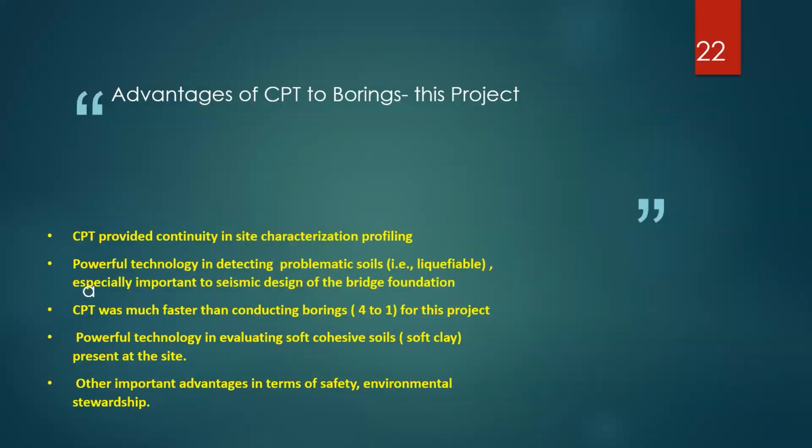So, advantages of CPT over boring on this project: it provided continuity, right? It is a powerful technology in detecting problematic soils, be it liquefiable or other problematic subsoils. It's much faster than conducting borings, almost 4-to-1 as measured on this project. It's also a powerful technology in evaluating soft cohesive soil, soft clay, which was present at this site in some of the bridges. And there are other important advantages in terms of safety and environmental stewardship.